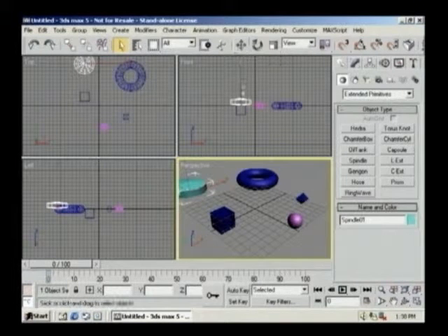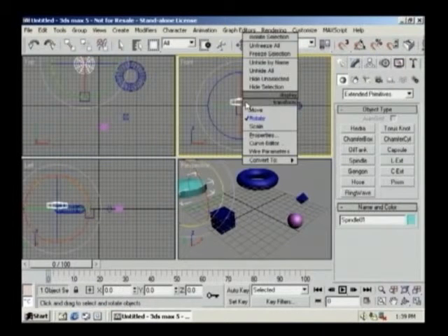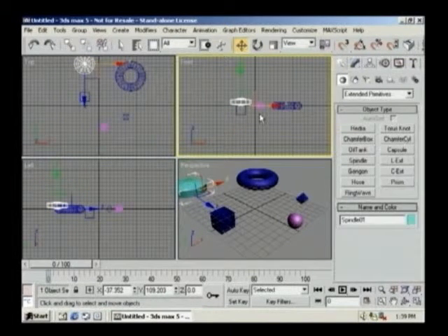To move an object, you activate the Select and Move tool, and then you select the object, and the Transform gizmo appears. Again, if you've used earlier versions of 3ds Max, you're going to see some changes on this transformation gizmo. More on the scale and the rotate transformation gizmo, but there are some changes also on the move transformation gizmo. But let's start talking about it.